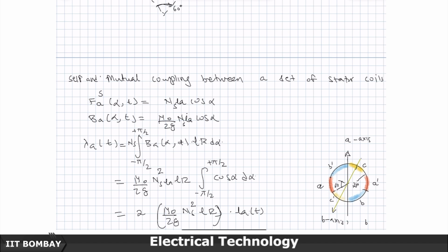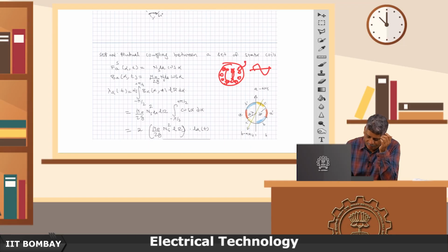Now, I am linking back to the previous lecture, and I am going to calculate the electromechanical torque which is generated on the rotor. Current is being fed in the A phase winding, B phase winding, C phase winding, and I will assume that the magnet on the rotor is set up as an electromagnet, a distributed winding which creates a distributed flux, and for that it requires a necessary current IR, which is the DC current.